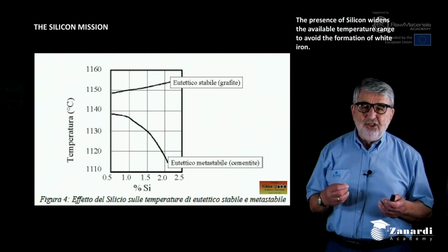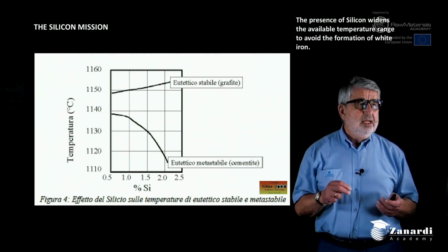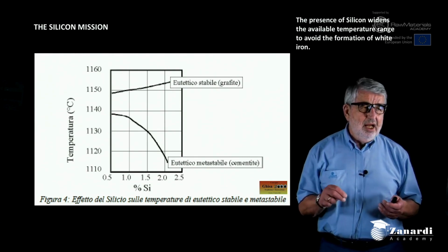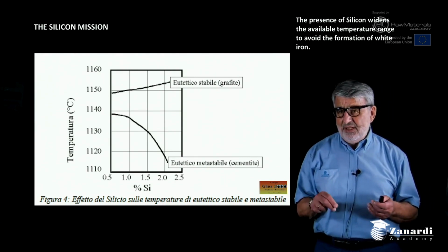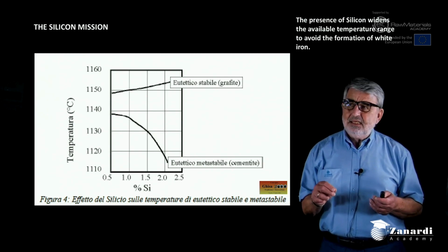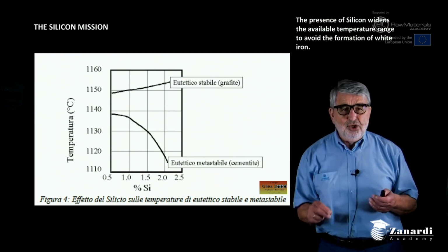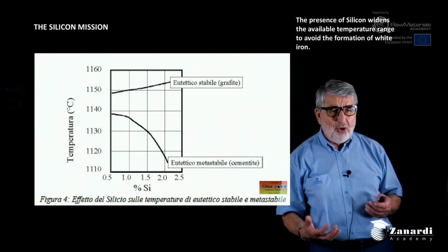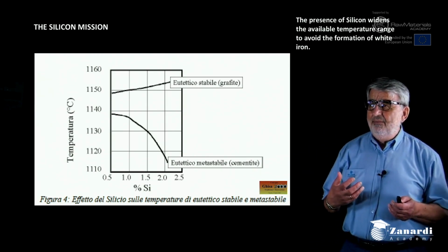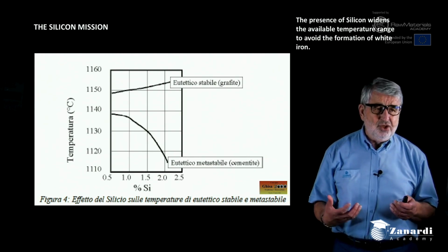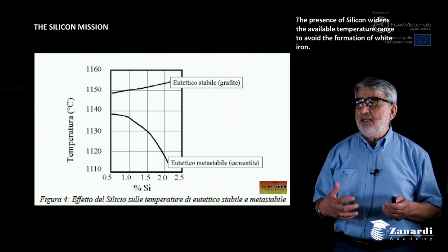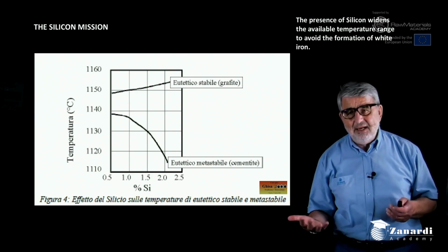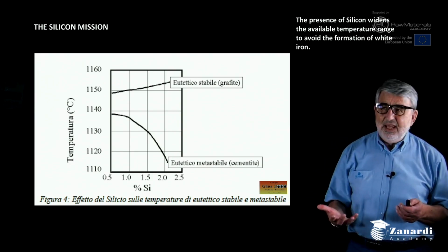That means the addition of some silicon and other elements into the liquid melt before freezing, and this makes external heterogeneous nucleation that accelerates the process of solidification in a separate form between the iron matrix and the free graphite.